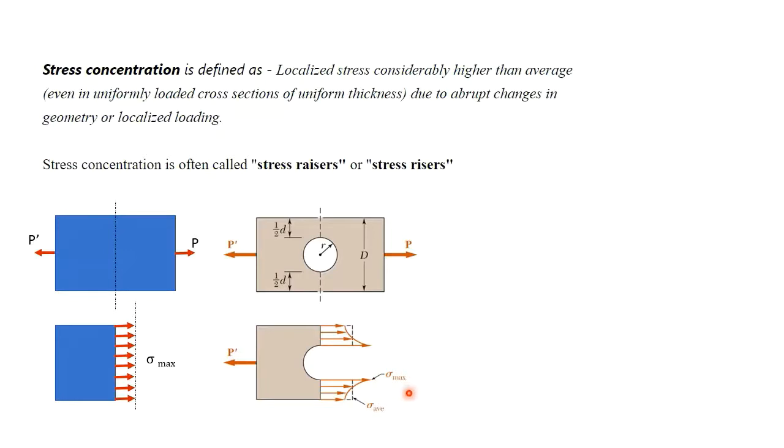Now here you could see this maximum stress value is definitely greater than this maximum stress value. What it indicates is that this part will definitely get failed earlier than this part. The maximum stress is getting induced, so there might be chances the crack will develop and propagate and the plate will fail.